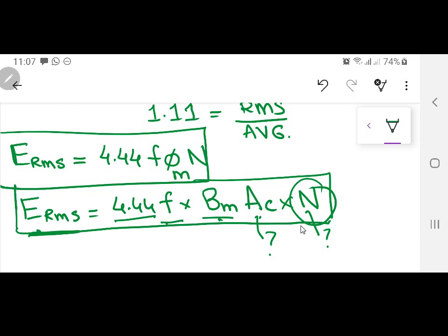But practically on the secondary side you will keep it a little bit more, because your transformer is being made, you are going to have losses, you are going to have voltage drops. So instead of 260, maybe 270, 280, a little bit higher, so that even at load that transformer is still giving you double the voltage. Okay? So this equation is the first building block for any machine, either a transformer or even a machine.